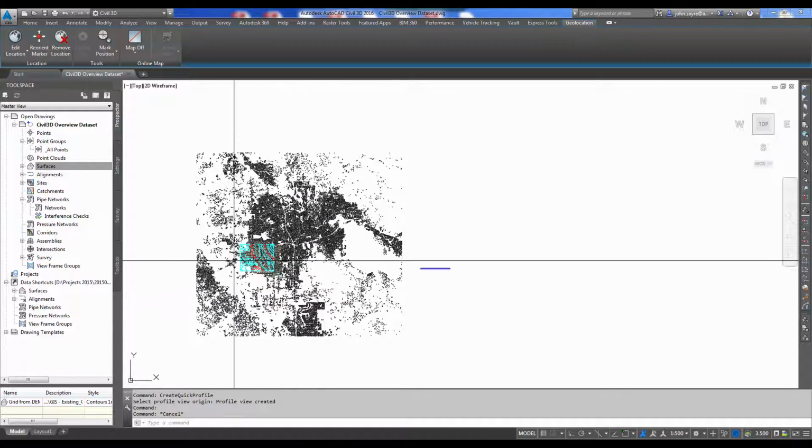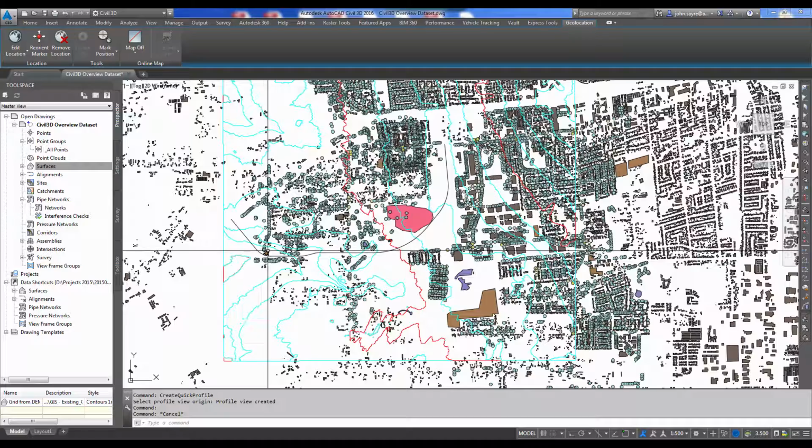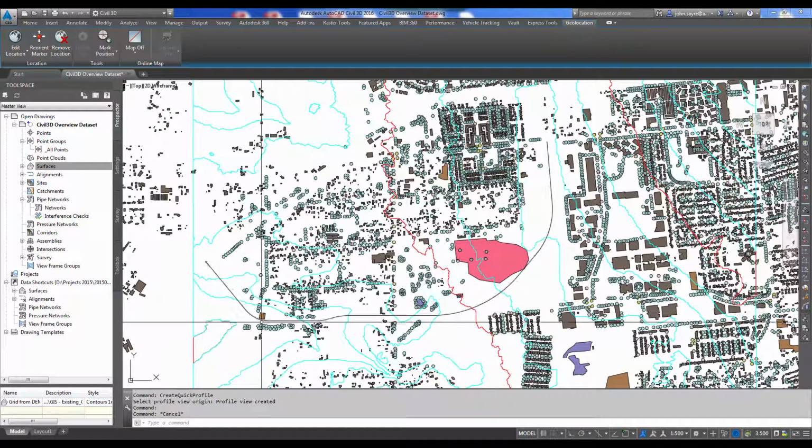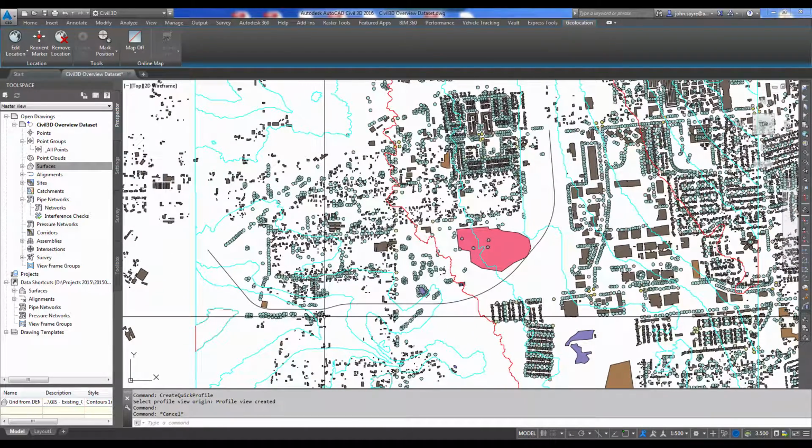So now that we have our location, we can go ahead and narrow down the scope of our topo that we're going to have the surveyors go out and get. And they've gone out and they've located topographically some of the structures that are inside of the actual area that we need. So we don't need this big giant topo that we used preliminarily, but we're going to narrow it down to a detailed topo of just this area. We might actually do an offset and tell them to pick up everything inside of 100 meters on the north side and 100 meters on the south side of the roadway alignment, just so that we know we have enough. And I think that's probably going to be good enough for the topography for the design road. So we'll go ahead and look at what they've picked up.